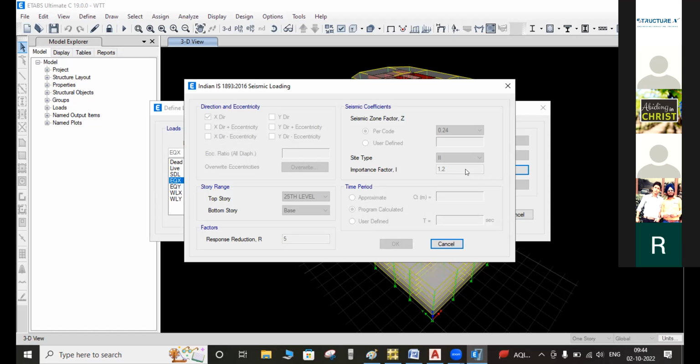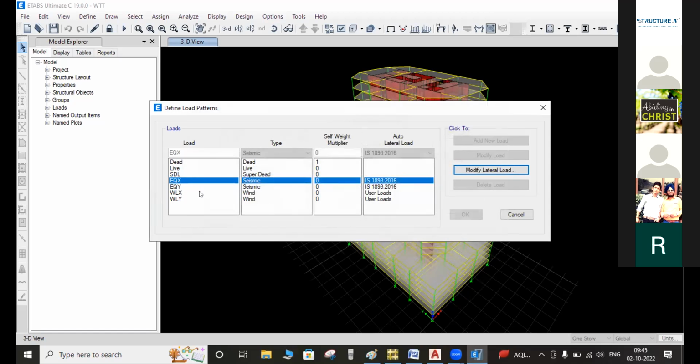That you have to define throughout the course, and after that we have to apply on the model, right? And after applying this seismic and gravity load, what will be the next procedure that we have to follow? Basically, sir, in a linear static analysis, we have to identify the base shear.